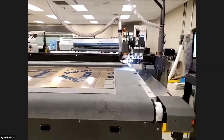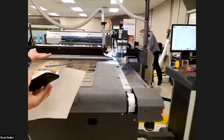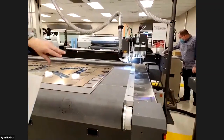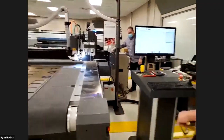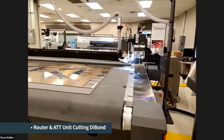Do a little router warm up right here. So Jim is doing, we didn't have the router on, and as is with any routing system, you want to do a router warm up. So that's all automated. Jim starts the router warm up, and it just brings the bearings up to temperature before we start actually routing.